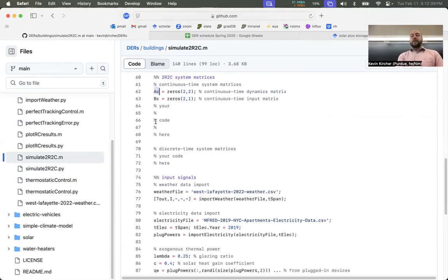And then once you have those, you should have fairly simple formulas. I think we may have already done related formulas in past homeworks, that convert the continuous time matrices into the discrete time matrices. So that would be using, for example, the matrix exponential. You could also use a MATLAB or Python built-in function, C2D, continuous to discrete, for linear systems. Did that address your question?